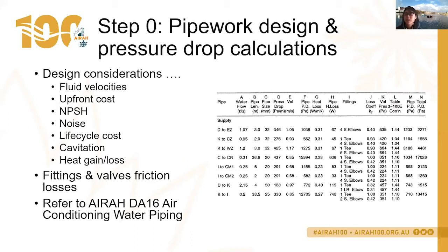When you're doing your pipework design, you would probably be considering what your fluid velocities are to avoid air entrainment. You'll be considering what the upfront cost might be based on your design. If you had lots of large pipes around the system, it might actually end up being really expensive in terms of upfront cost.